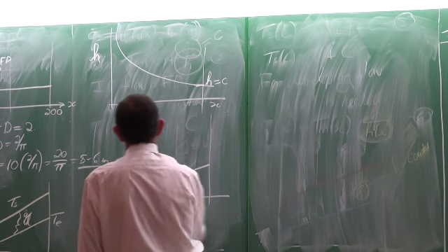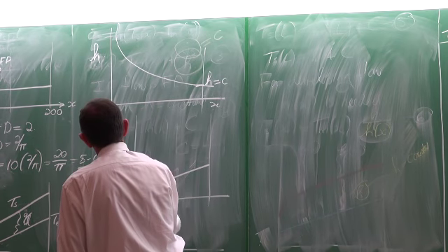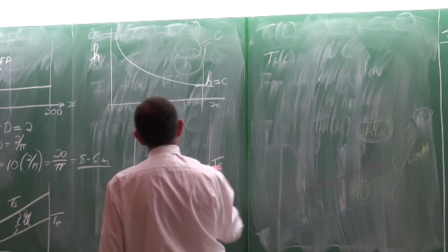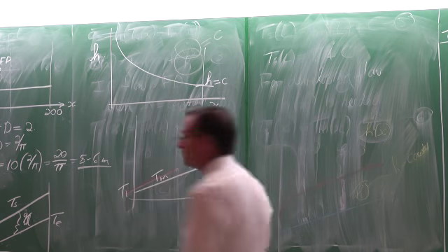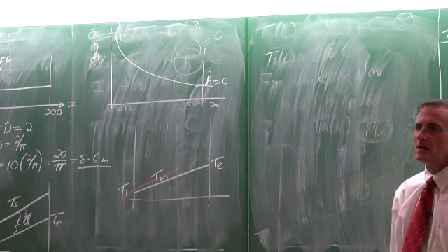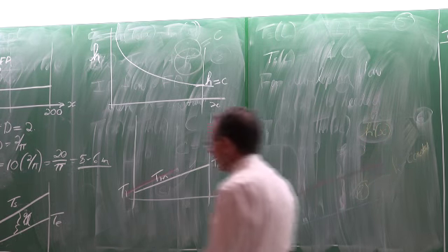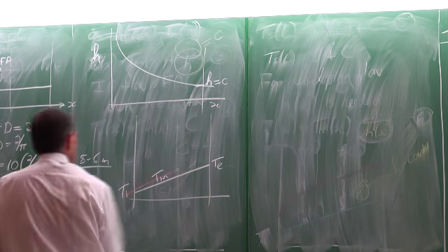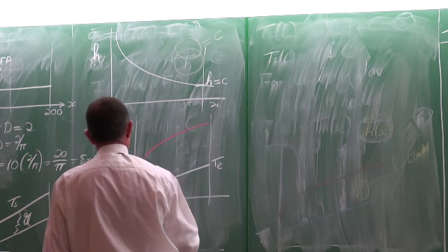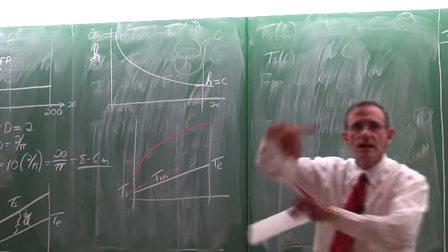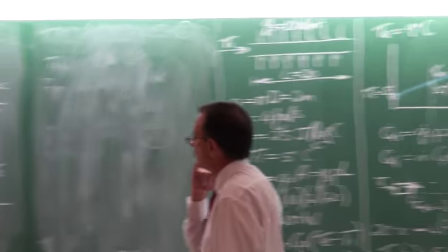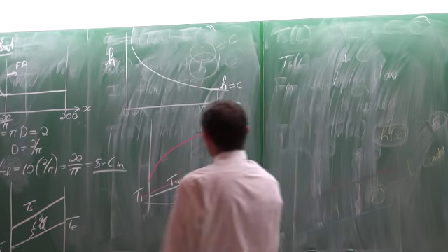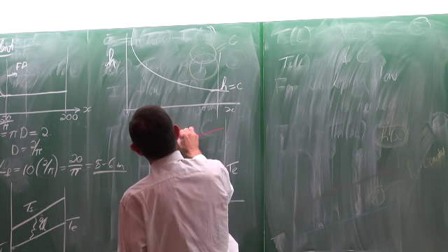We know that the fluid temperature is going to do that from inlet to outlet. That is going to be the mean temperature. And the surface temperature now is going to do something like that. So there's almost never a constant value of Q divided by the heat transfer coefficient between the fluid and the surface.